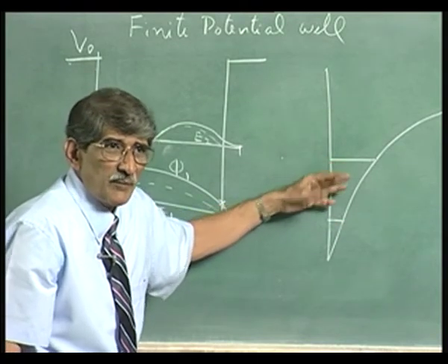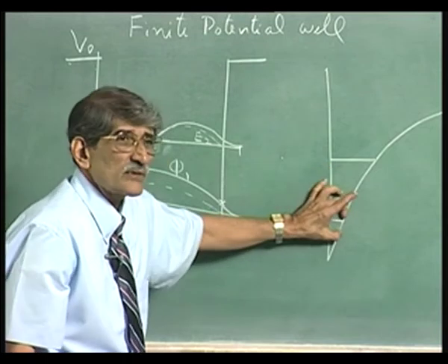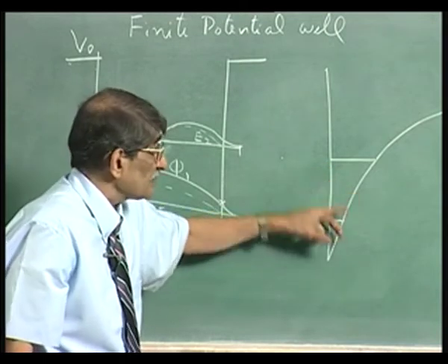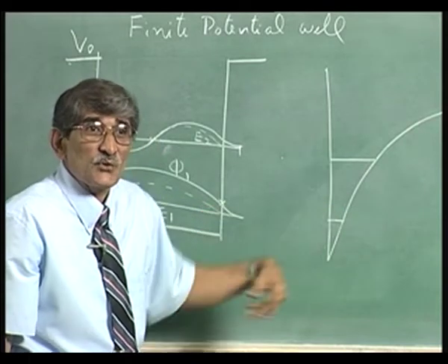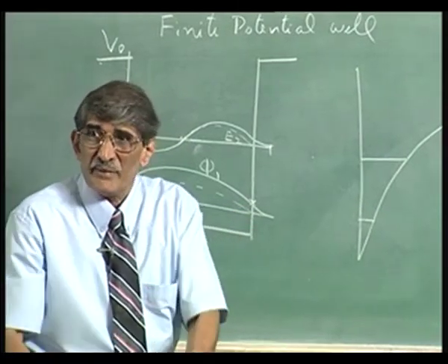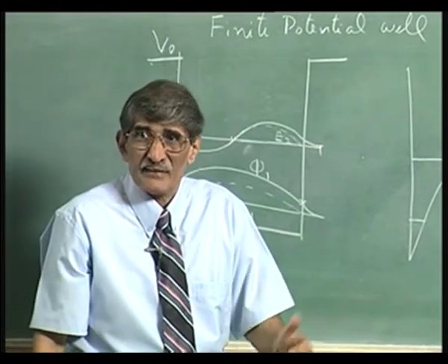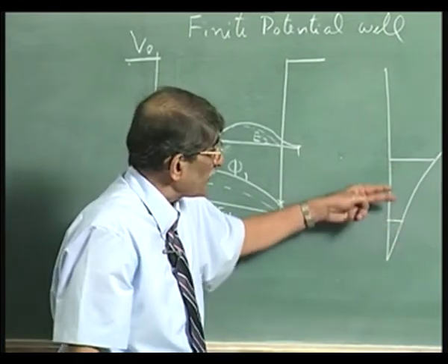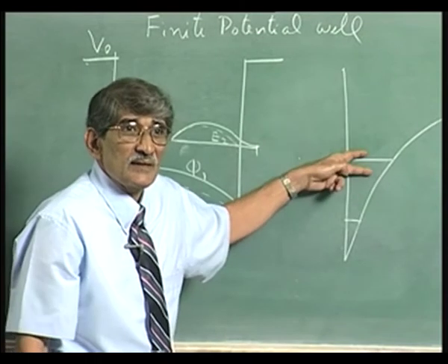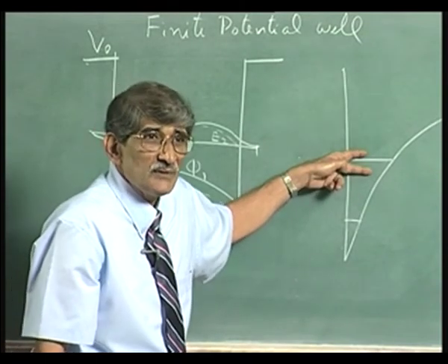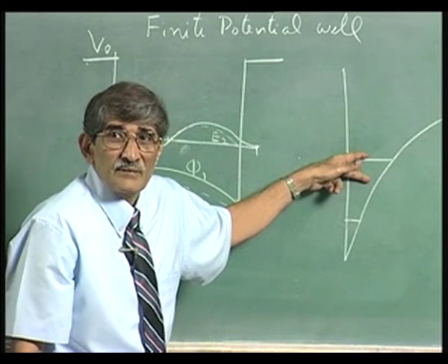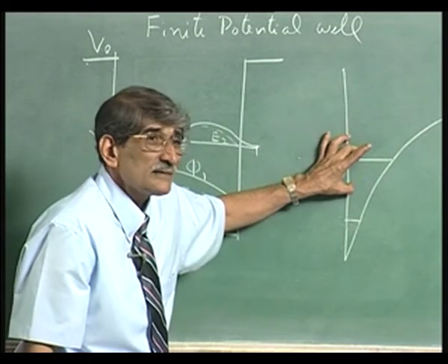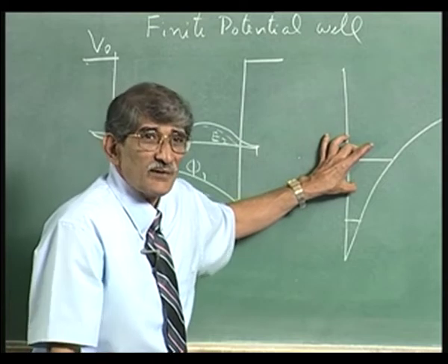So, the mobility, everything will be decided by this band mostly. There will be a difference in mobility of this subband and that subband. You know that as you go to higher and higher energy, the mobility keeps on falling in the higher energy band levels. So, mobility of electrons here is better compared to mobility here. From this point of view, you would not like to dump electrons into this subband. If many electrons are resting here, the average mobility will fall down.